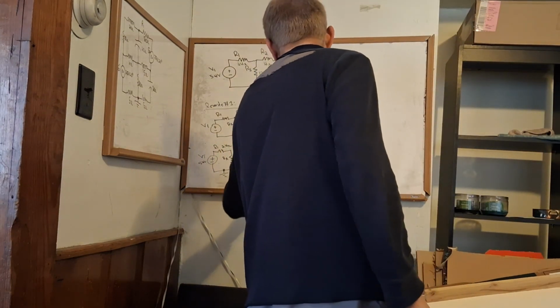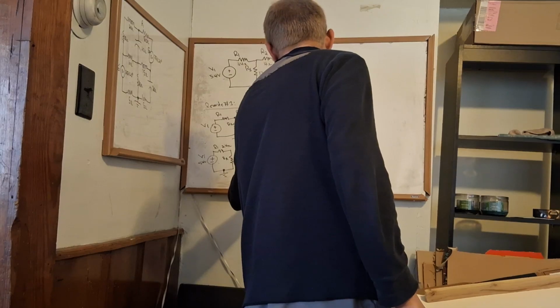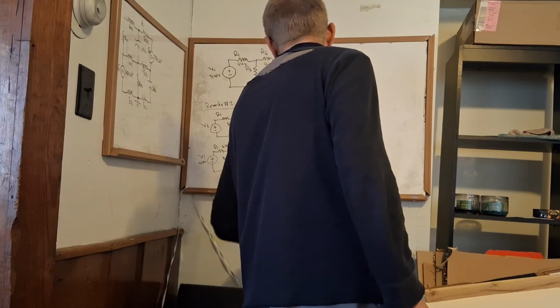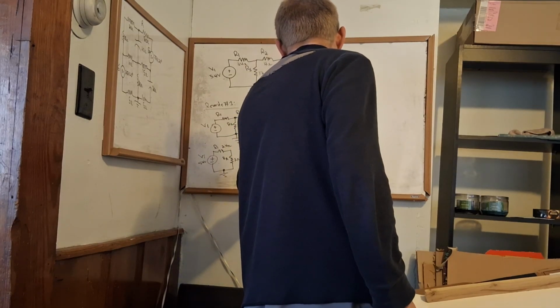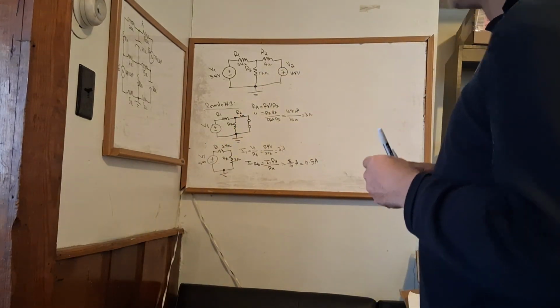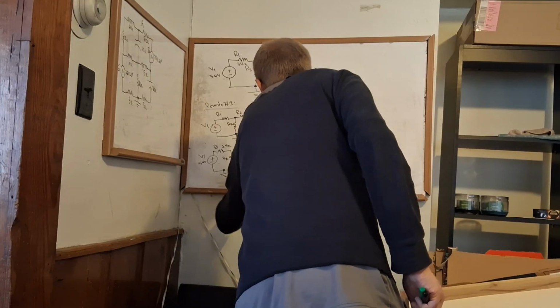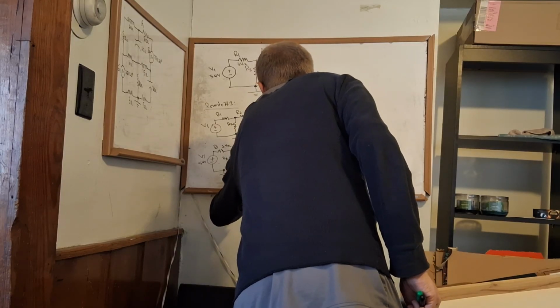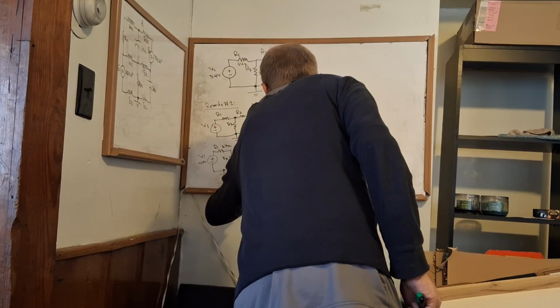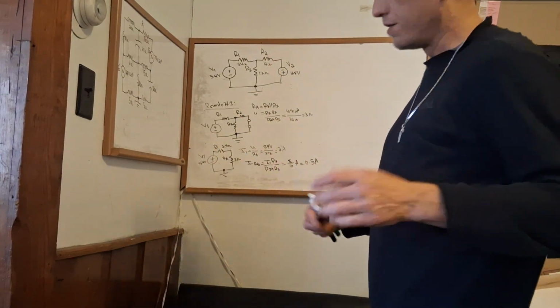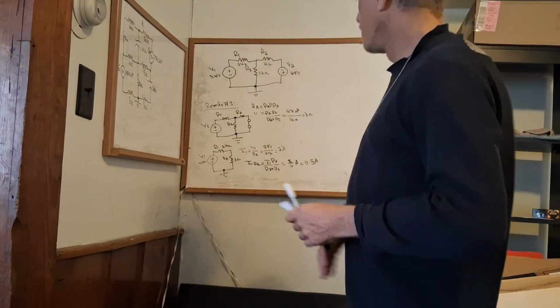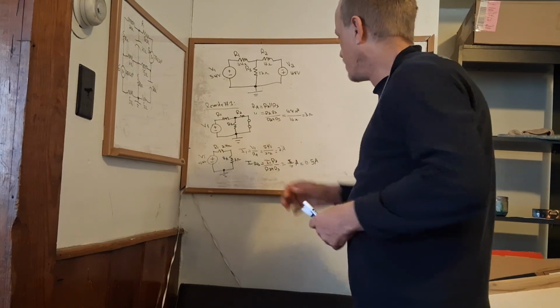Oh no, it's the sum of these two. It would be the sum of these two, which would be 16, which is 0.5 amps. It's not RA, it's R2 plus R3, the sum of those two. I was thinking parallel circuit, but the current divider formula is different than the parallel circuit. The parallel circuit is product over sum of the two.